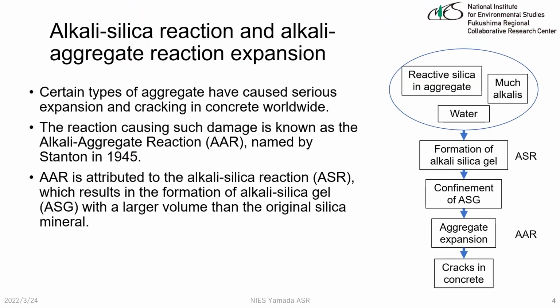The reaction causing such damage is known as the alkali aggregate reaction, AAR, named by Stanton in 1945. AAR is attributed to the alkali-silica reaction, ASR, which results in the formation of alkali-silica gel with a larger volume than the original silica minerals.